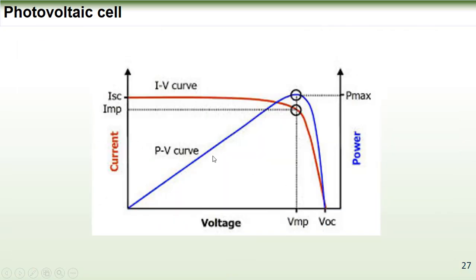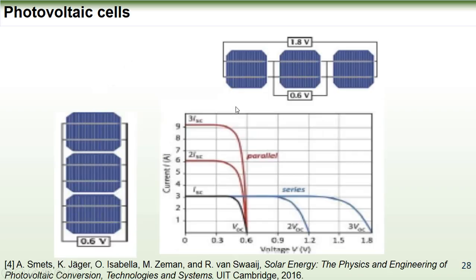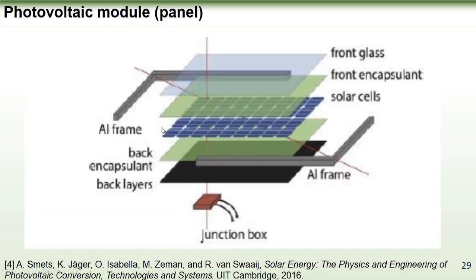reduced. Since the temperature and the irradiance vary around the day, and in order to capture the maximum power from each cell, the maximum power point changes, and the system has to track that point continuously. As we mentioned, each PV module consists of several cells connected in series. The IV curve of the combination is changing accordingly. When more than 1 PV module are connected in parallel, their combined IV curve is changing as well.